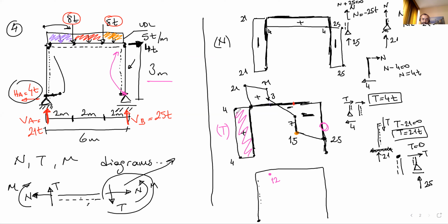Since the shear is a horizontal constant line, that means if this is a constant value, we are gonna use a 1 degree curve on the moment diagram. So it's a line. Let's connect these up. I couldn't do that. Let me do it with this. That's better. Okay.